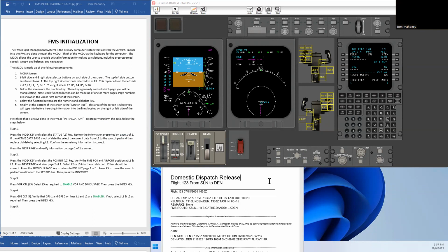When we're convinced we're on the right aircraft and we've completed a safety check, then we will turn the master battery switch on, power up the APU. Once we get electrical power onto the aircraft, our panels will start to show us display information, and we are ready to go and initialize the FMS. We do the initialization of the FMS through our MCDU over here.